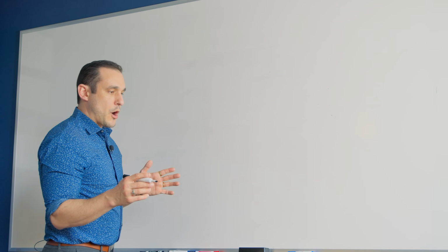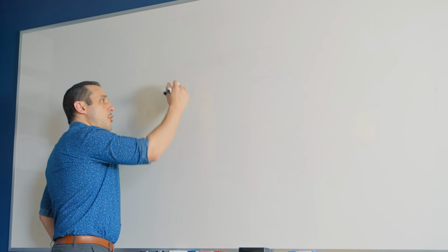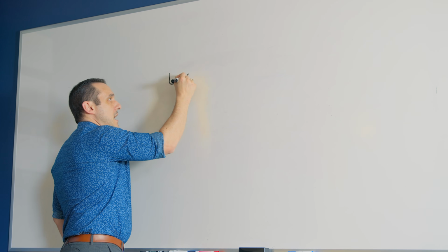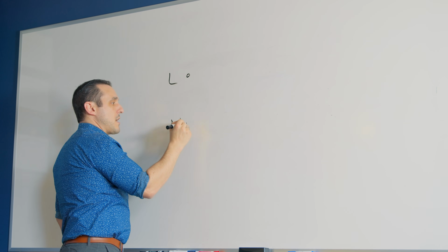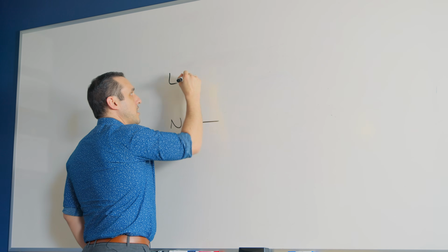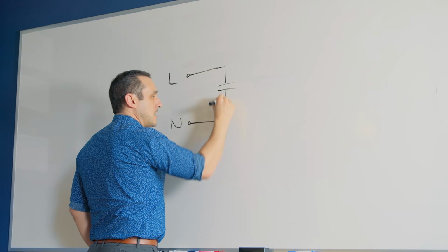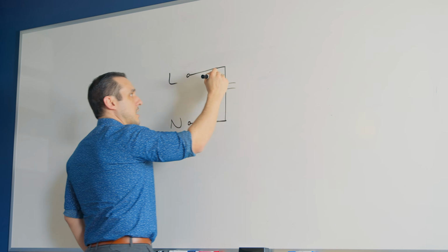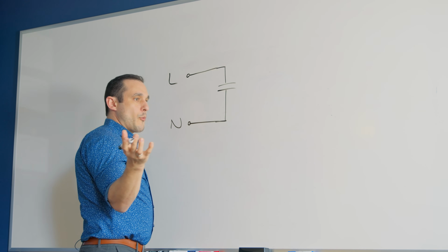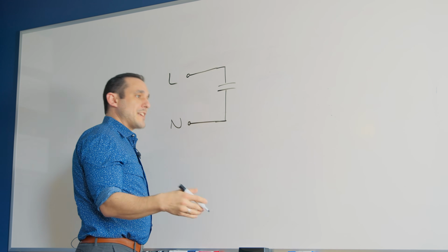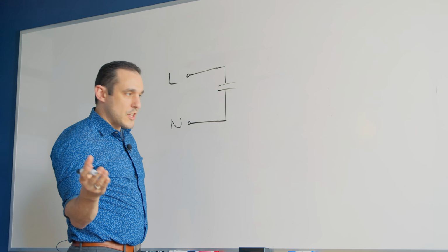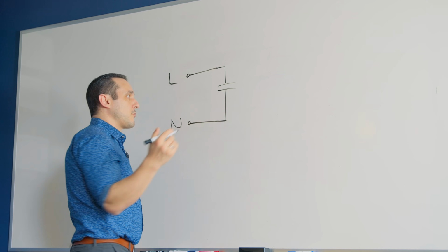So the basic EMI filter circuit topology that we want to use with an AC input is going to be a low pass filter. So first we have our line input, and then we have our neutral, and we're going to come in and first go to a line-to-line capacitor. So that's the first thing we're going to hit. And then if we're doing low-pass filtering, we generally would like to do a pi filter because that's going to give us much stronger roll-off at high frequencies.